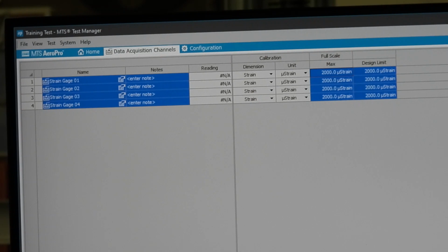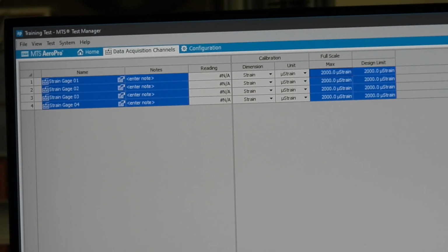No, because now I'm not an expert at scale measurement, but I thought that the full scale is somewhat arbitrary in terms of the definition of the scaling. I don't think that when you're defining a strain gauge, the full scale value you're putting in here is changing the scale factor or the conditioner gain.